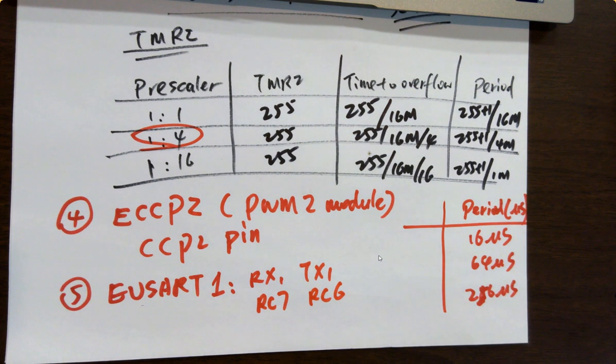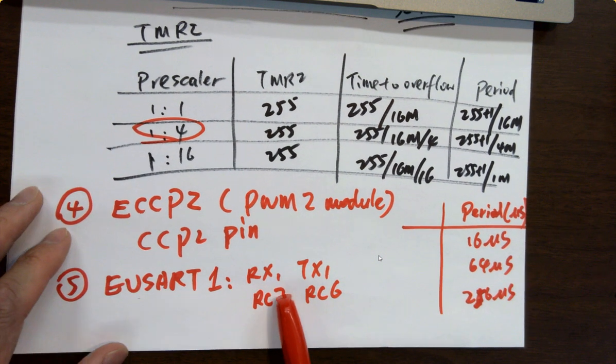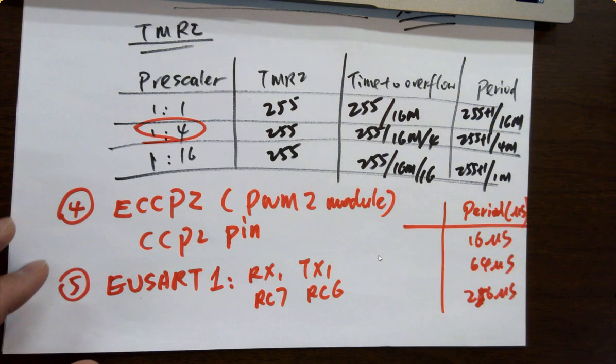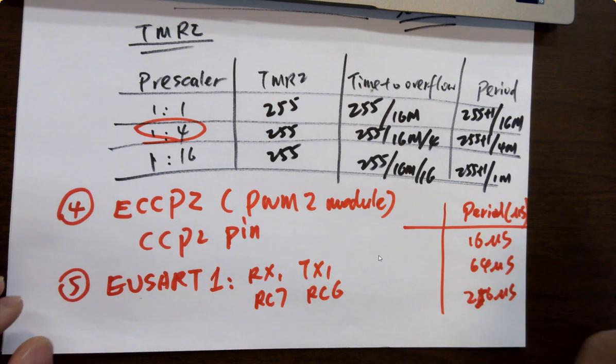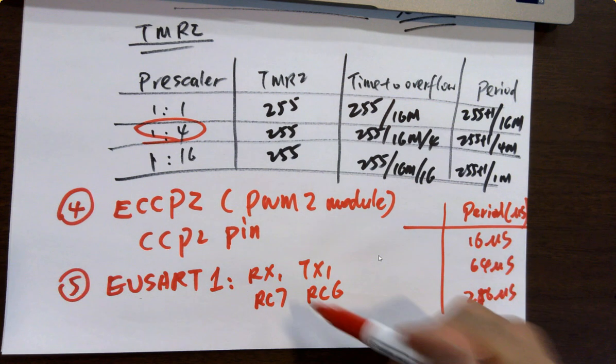Do we really care about it? Do you really need to do something to it for these? Or by far, have you done anything to it? Why? Because it's already set up. It's hardware, connected on the PCB. So that is a UART port connected to your laptop. If you plug in the USB, you see the signals from PuTTY, or you can send or receive signals through here.